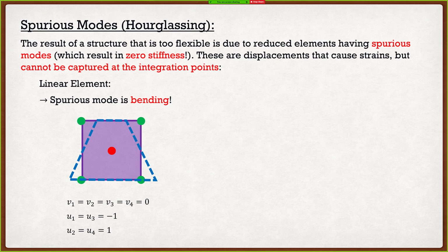This is actually a problem. Because if we were to look at our integration point right here, it's right at that transition from compression to tension. So therefore, at that integration point, there are no strains. And then mathematically, you're saying, well, if there's no strains, then there must be no applied forces. So this is where the problem starts to happen: if we do reduced integration, we might actually activate one of these modes where we're going to predict 0 stiffness under certain deformations.